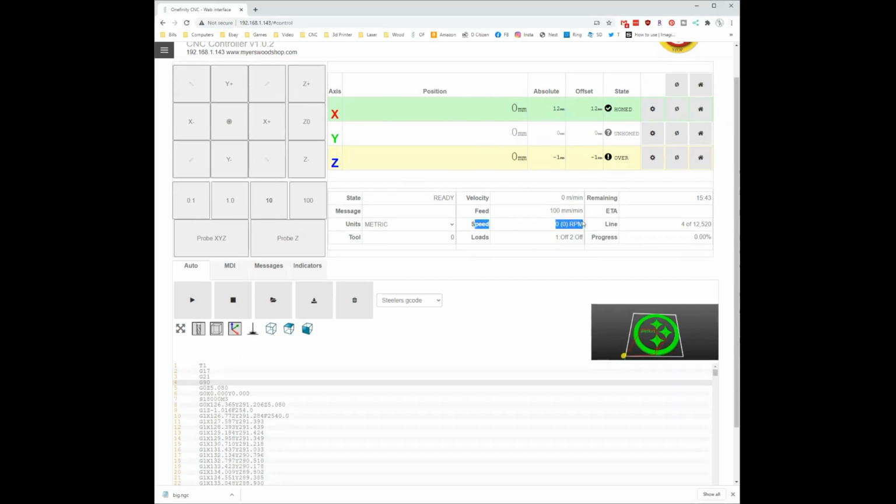So the speed here is going to show you the RPM if you have a spindle connected, or if you have a laser. Did any of y'all get a laser or a spindle? I ordered the laser. You did? Yeah. Okay. So for the laser, usually the router shows an RPM, but for the laser it'll go from 0 to 255, and that's power. So 255 will be 100% power, and 0 will be 0% power. That will only be relevant if you plug in a spindle or a laser.